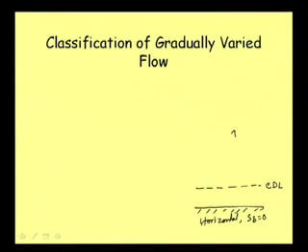Fine. Then what about the normal depth? We have already discussed that over a horizontal channel we cannot have a normal depth. It would be at infinite distance from the bed. So the normal depth line we cannot have, we will say that yn is at infinity.